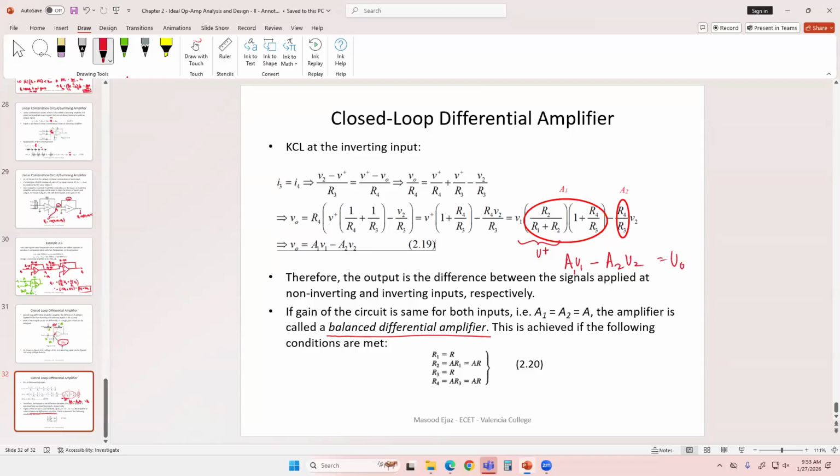If it is asked to do the design, like we did the design of the summing amplifier, then you'll have to show the design. You can choose your own resistor. Usually I give a range. Choose a resistor range between 1 kilo ohm to 10 kilo ohm, for example. So you can choose any resistor value if you're making a specific design. Because for design, you can have your own value based upon what resistors are available.